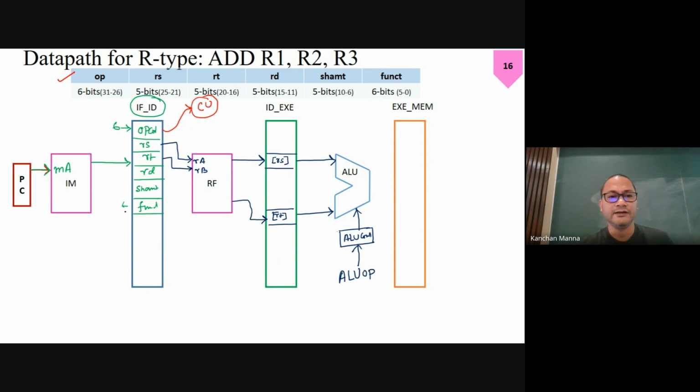We have the func field here, right? But in this stage register, we don't have the func field. So what do we have to do? We have to create space for the func field. And then the connection would be like this. It would come via here, right? We can't directly forward it from this, because we want to split the entire stage into 5 parts. Okay. Got it.